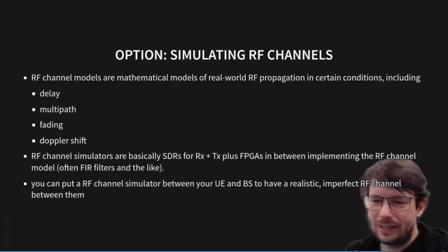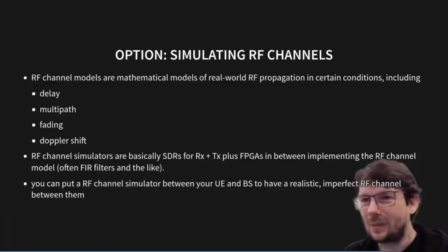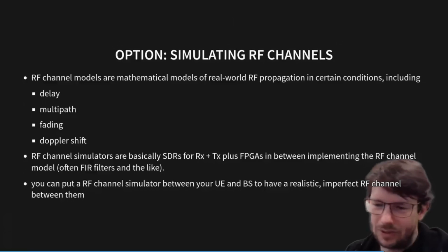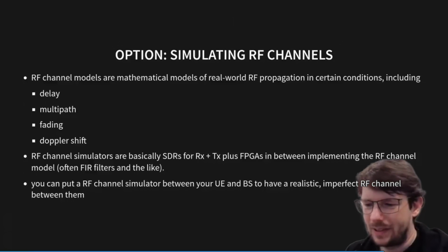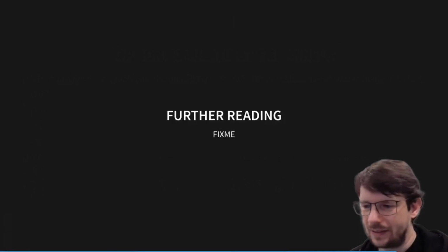And they simulate not just the attenuation that you could do with a step attenuator, and not just the delay like the Osmo RFDS, but also multipath fading, Doppler shift, and other effects. And yeah, you can just put a simulator at any point in such a network, always keeping in mind the input and output RF power levels, and then have such simulation capability in such a wired test setup.